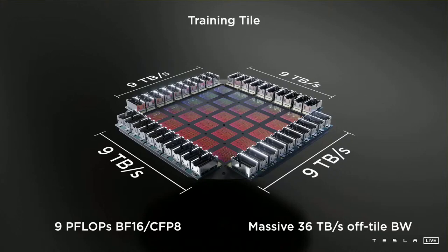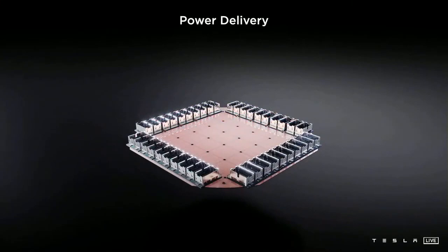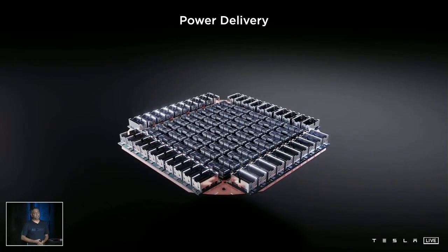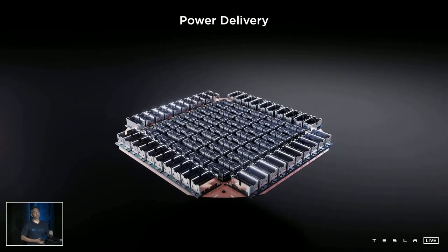Now that we had our compute plane tile, with high bandwidth IOs, we had to feed it with power. And here, we came up with a new way of feeding power vertically. We created a custom voltage regulator module that could be reflowed directly onto this fan-out wafer. So what we did out here is we got chip, package, and we brought PCB-level technology of reflow onto this fan-out wafer technology. This is a lot of integration already out here.